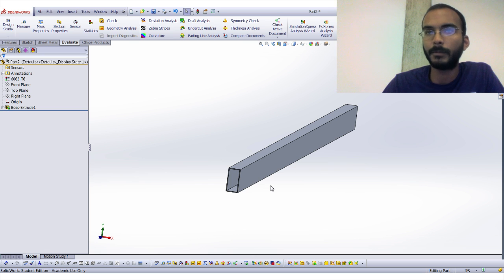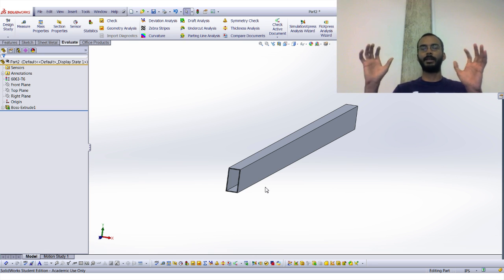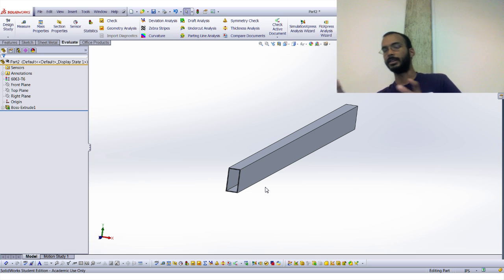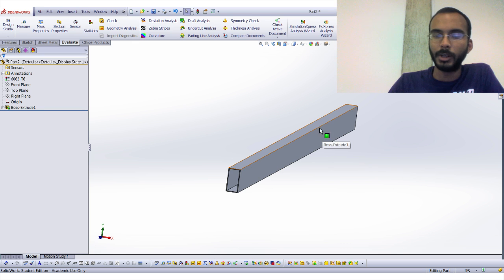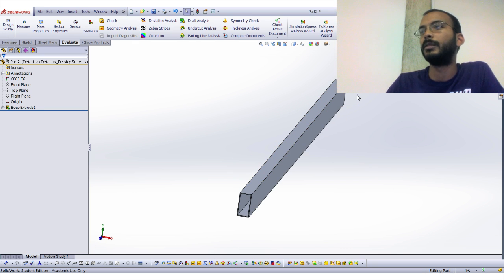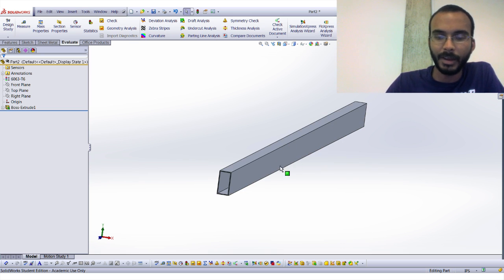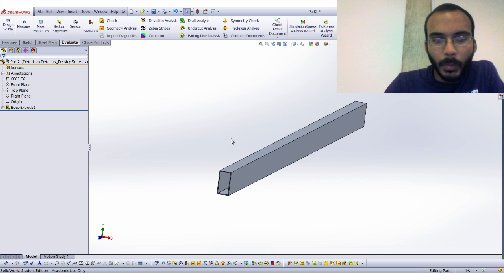When we start doing assemblies and things, and you put in a motor or something, you're gonna have to tell it how much that weighs, because it's not gonna know based on the density how much one of the things weighs. But once you put in those things, it'll add it all up for you, and you can get a pretty reasonable account of what the weight of your robot's gonna be, so you don't have to guess, and you won't be wrong when you actually get to competition. Okay.